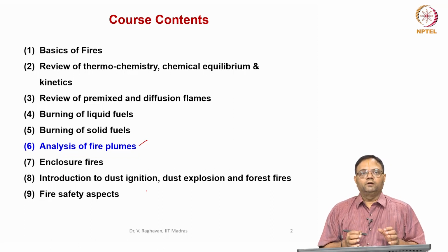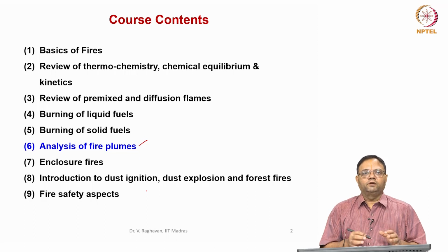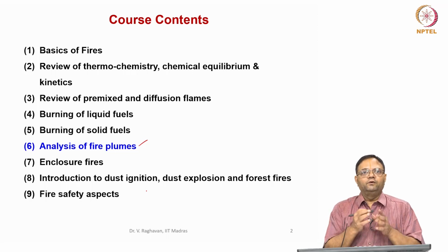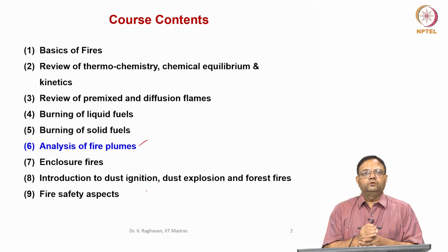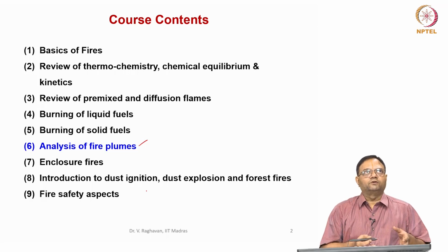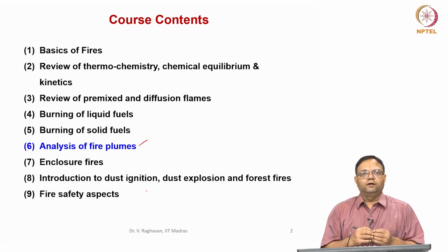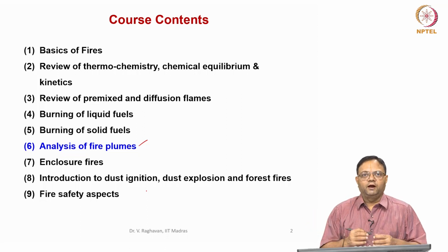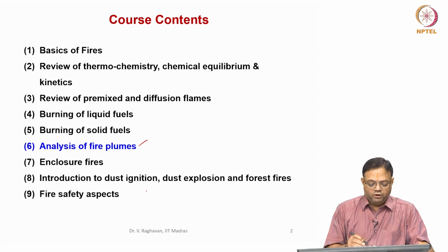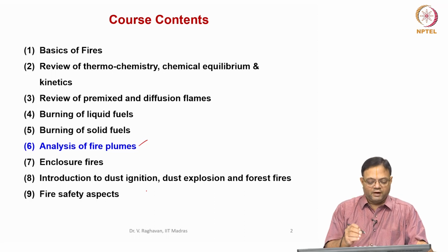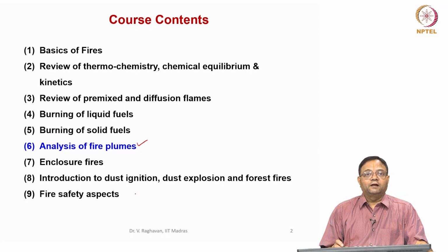So within a compartment, if you have a fire, based upon the size of the fire, you will see that the hot gases are formed, the smoke is formed, and the smoke actually rises up and hits the ceiling and actually spreads over the ceiling and descends down, etc. So a lot of dynamics are there for this. So to analyze the strength of the hot gases which are rising up, we need to understand what a fire plume is and how the characteristics of the fire plume are defined.